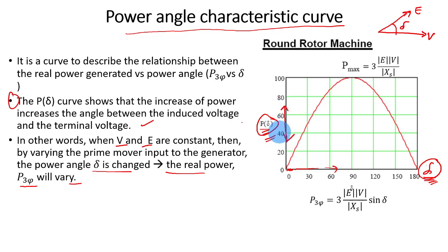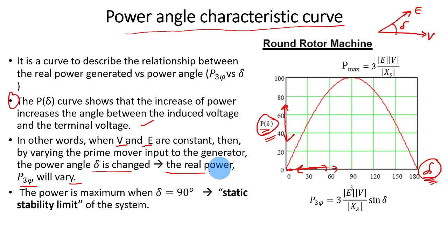So it depends. Sometimes the generator can go up in power and move between this angle and this angle. Typically the generator will operate below this maximum value. What I didn't mention yet is, what is actually this point here? This point here we call the maximum power, which is basically what we call the static stability limit.